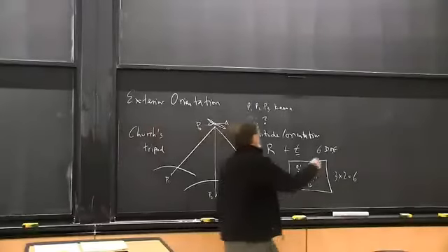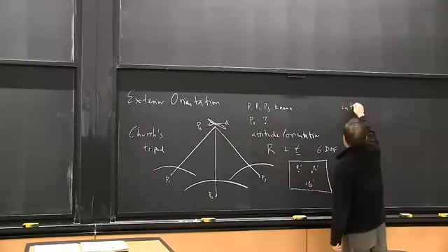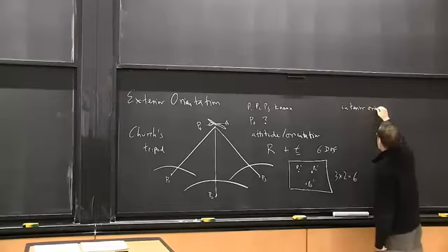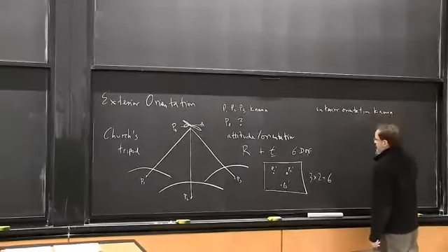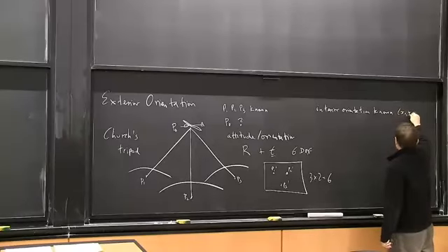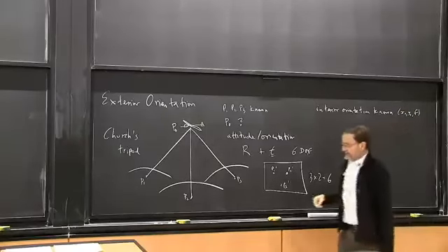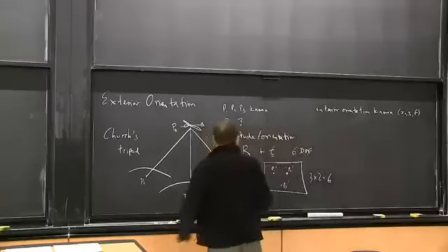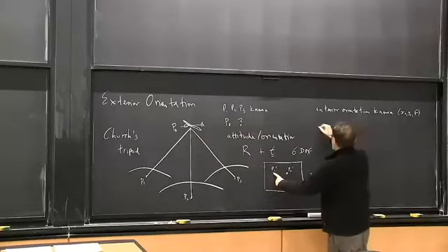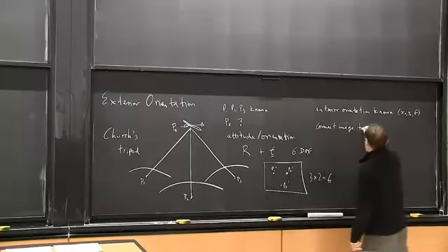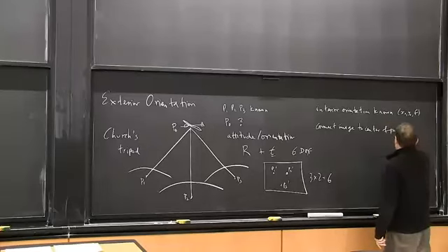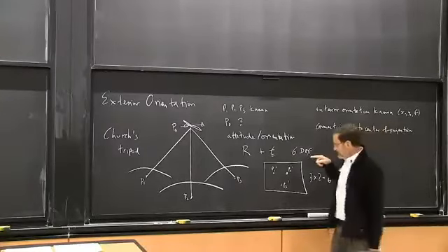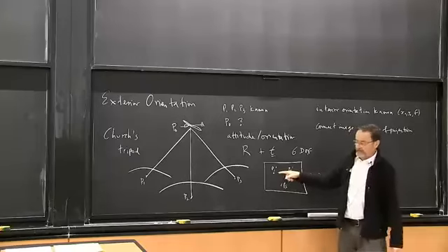Well, let's assume that interior orientation is known. So that means x naught, y naught, f are known. And so then when we have a given point in the image, we can just connect image point to center of projection. And we have a ray in space. And we know that the object is along that ray in space.